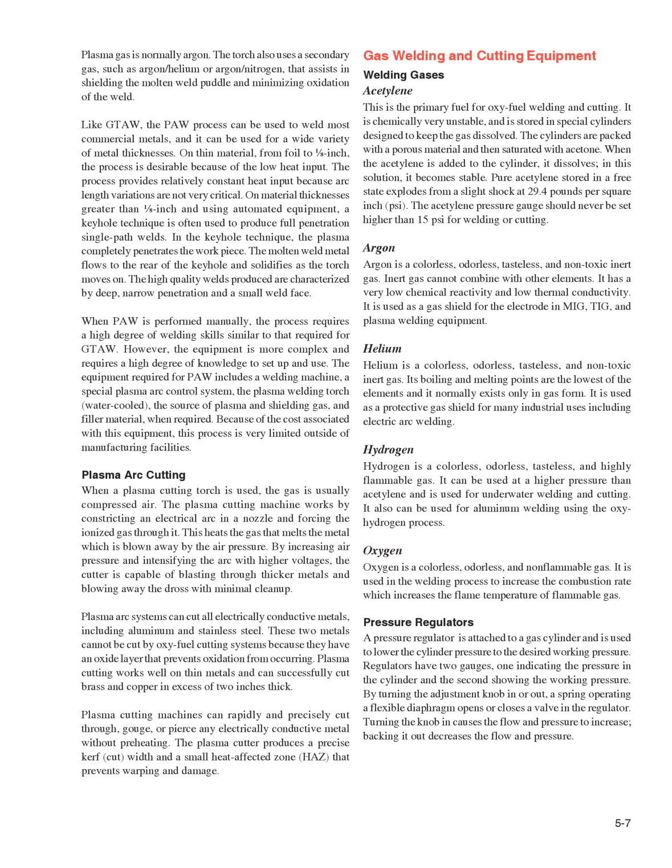On thin material, from foil to 1/8 inch, the process is desirable because of the low heat input. The process provides relatively constant heat input because arc length variations are not very critical.